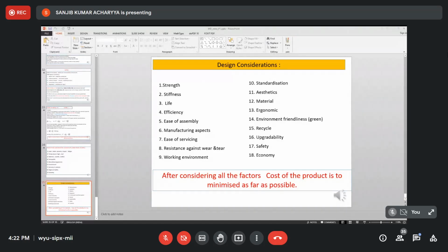Feasibility, castability: there is no very specific procedure to measure them quantitatively, but there are a lot of aspects of material property which can give you hints whether machinability or castability will be more or not. Because during the casting procedure, what material properties are favored, those are noted. Suppose the fluidity of the metal, and shrinkage, how much volume shrinkage there will be. The higher the volume contraction rate, the lower the castability, because then there will be a reduction in size compared to the mold.